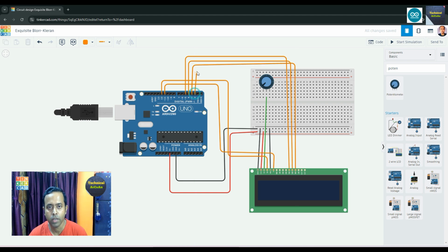And next one, another digital pin is there, which is D2, and connect with this particular pin. So 4 pins are left, and those 4 pins are connected with the digital pins respectively 5, 4, 3, 2. Okay. Next part is anode, so it's connected with the 5 volt with 220 ohm.